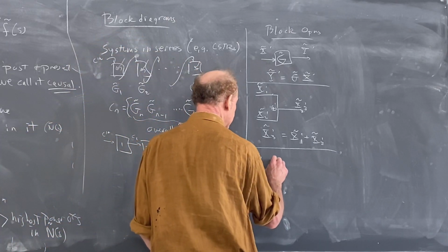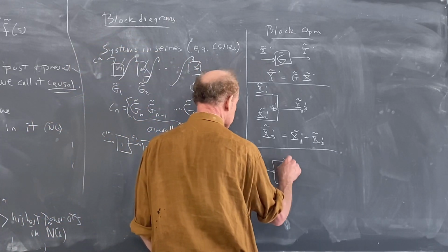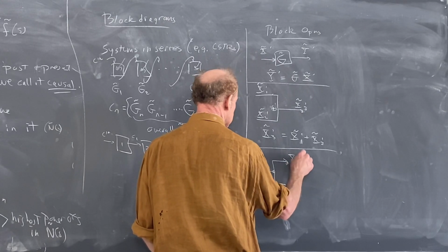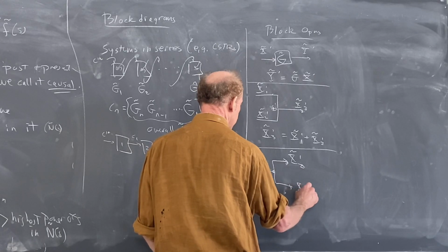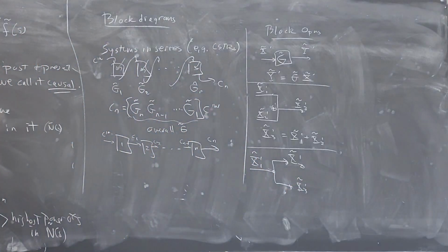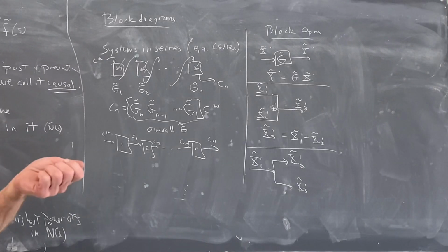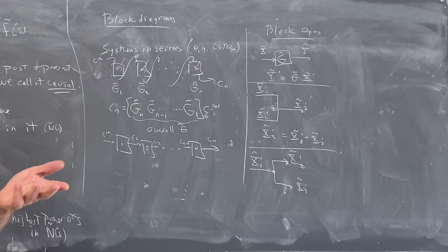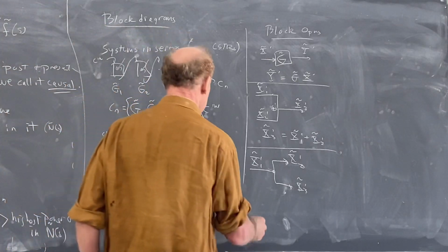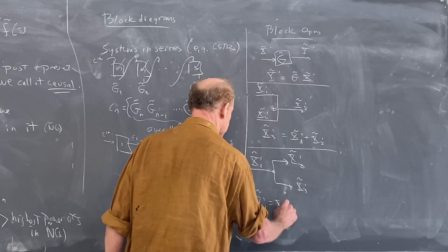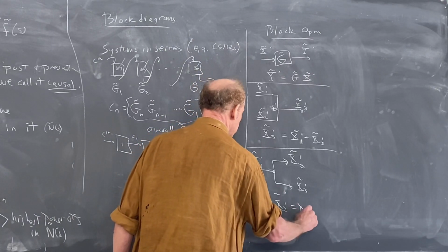So I take a stream and I split it into two parts, x2 prime tilde, x3 prime tilde. And you could think of this as an output stream from a reactor where I split it up into two parts. Part of it goes this way, part of it goes that way. If I'm looking at the concentration, that hasn't changed. So this tells me that x1 prime tilde equals x2 prime tilde is equal to x3 prime tilde.